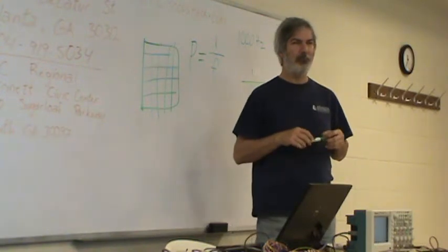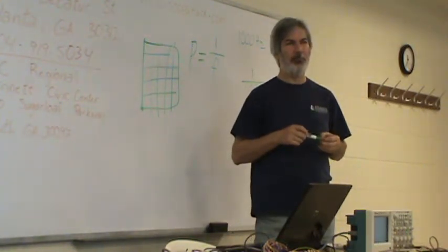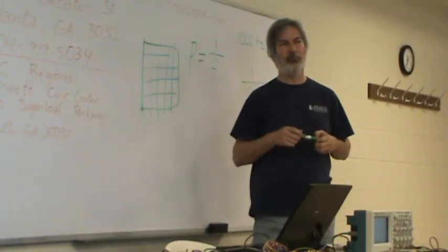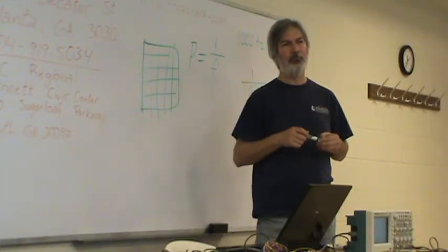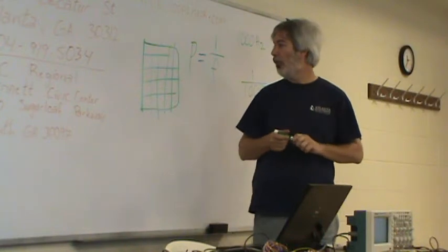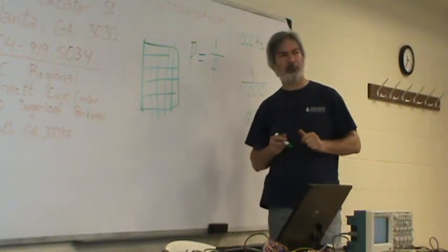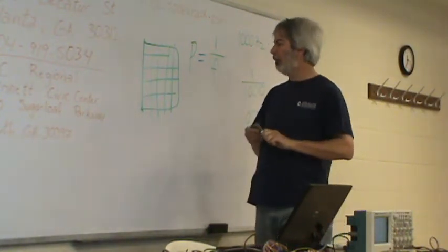Right. Same with the PWM oscillator of your circuit's motor. I know it's about 1,000 hertz. If you want to see your pulse width modulation signal, my parts have 5% variance, so I'm gonna be somewhere around 1,000 hertz, but how do I find out exactly what that oscillator is putting out using the scope? It could be putting out 990, it could be putting out 1,010.